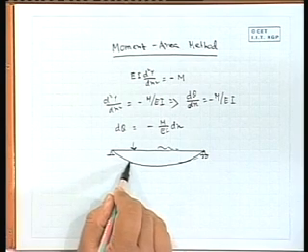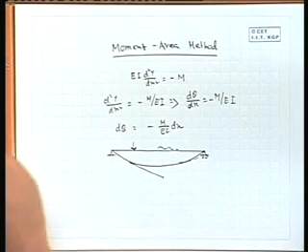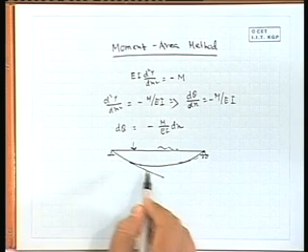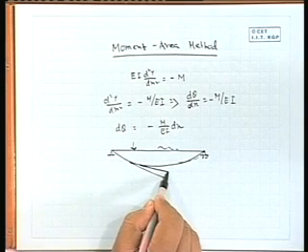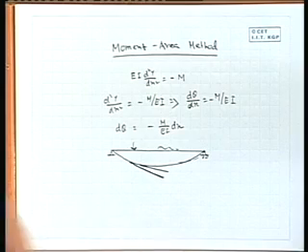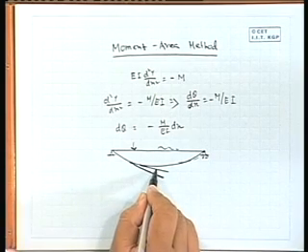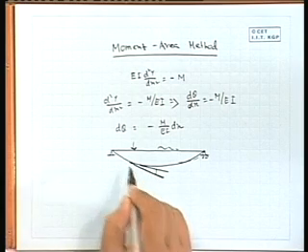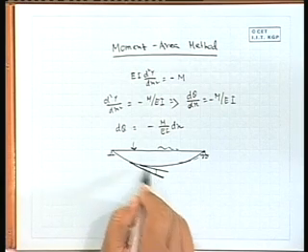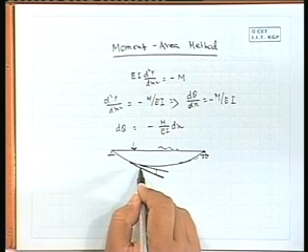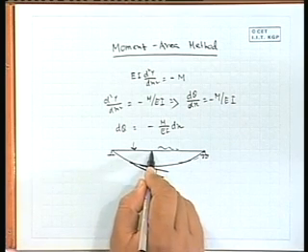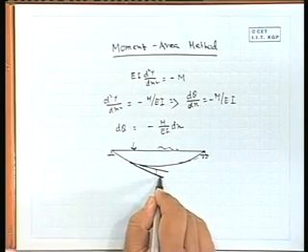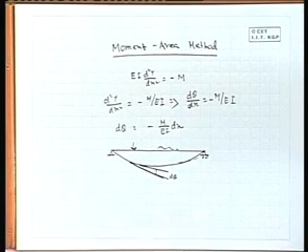If we draw the tangent on the elastic curve at that point, and if I take some adjacent point here, if we draw tangent here, the angle between the two lines is d theta, because this line with x is basically theta, and here this line with x is theta plus some increment of theta. So, this value is nothing but d theta.